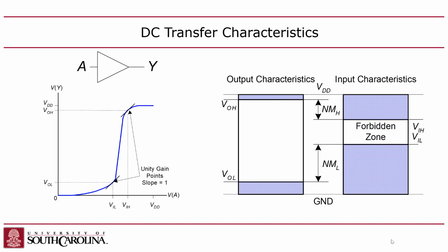So what you end up with is a noise margin, where you have an upper bound on the amount of noise that can be affecting a wire, which is the difference between VIL and VOL, because the gate is guaranteed to output VOL or less. You've got the output of a gate being fed into the input of another gate.